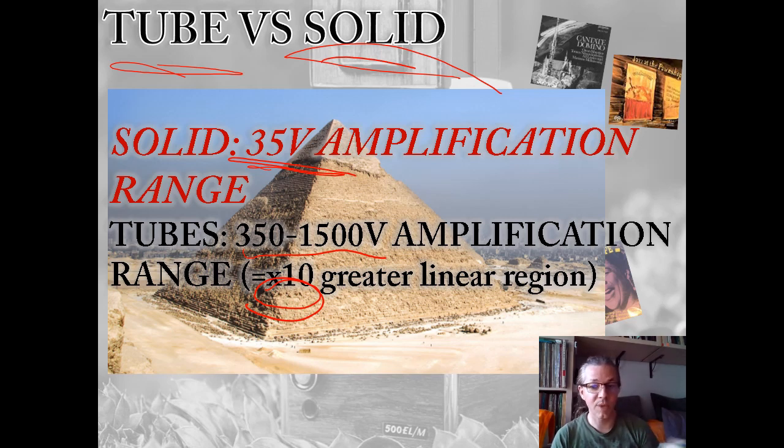And here people are saying, oh no, tube amps are noisy and stuff like that. That's how you execute it. That's a different issue. That's not because of vacuum tube technology. That's because of excessive cost cuts. So for any kind of amplification, either tube or solid state, you need to have a very quiet power supply. And if you have an equally quiet power supply for a solid state amp and a tube amp, now we are talking about business. But you cannot compare a solid state amp that has an exemplary power supply, and it's dead quiet, to a tube amp that was maybe made in China.